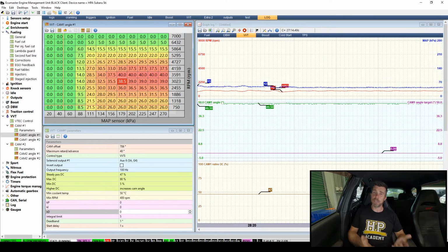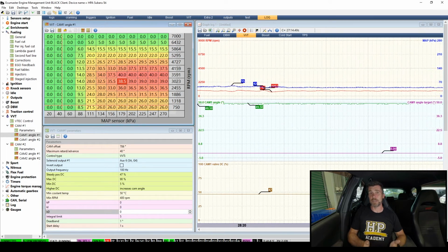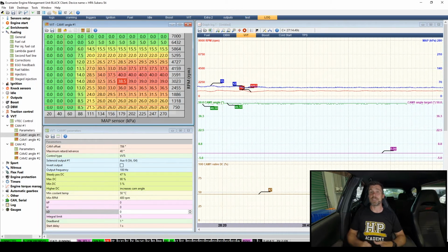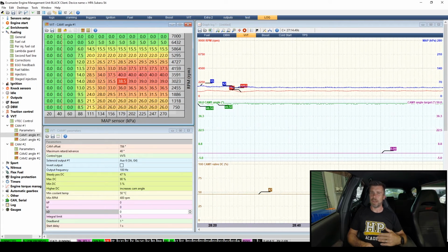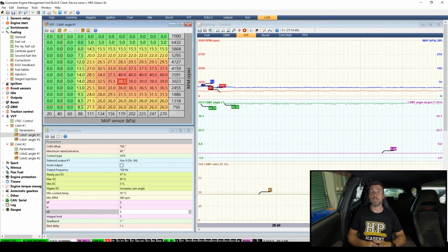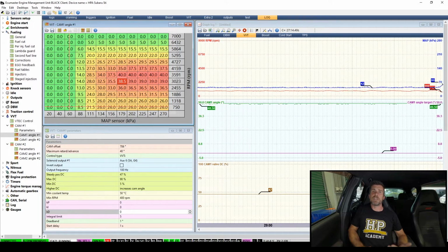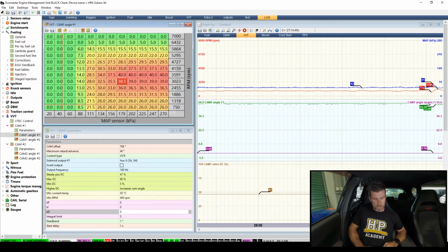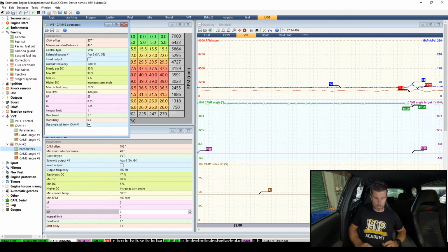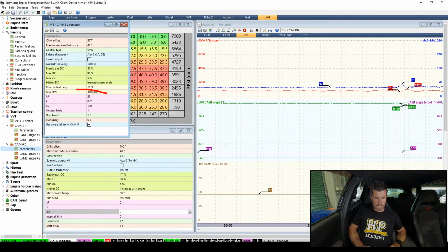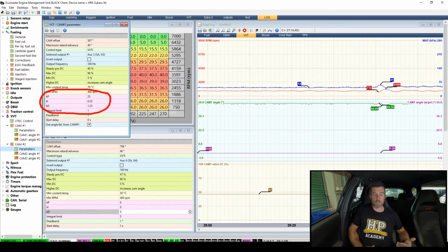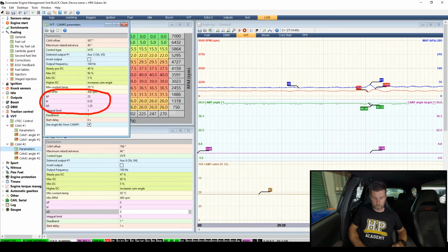So you can't take the gains that we're going to develop here for Ecumaster, apply these to Motec or AEM or Link or any other system and expect perfect results. They are very dependent on how the particular ECU manufacturer has implemented the PID control algorithm. To illustrate these numbers in the Ecumaster software, let's just bring up our cam 2 parameters. Obviously cam 2, the other intake cam. We'll double click on that and we can see here that we've got a proportional gain of 25, an integral gain of 0.25 and a derivative of 1.25.